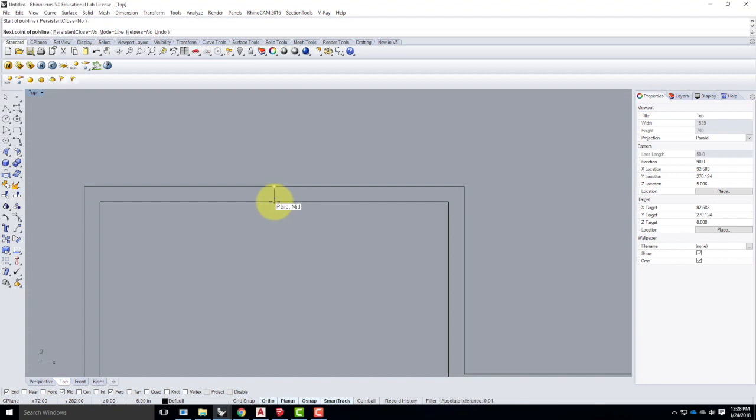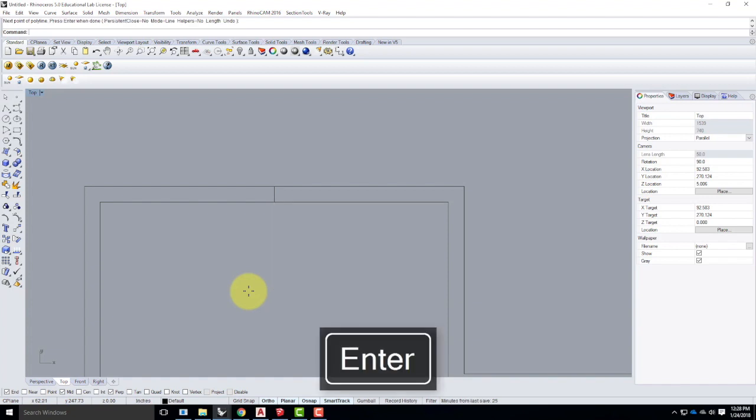But I also have midpoint, and this is the midpoint of that line. So both snaps are being used. Nothing wrong with that. I'll go ahead and click there. And because this is a polyline, I could keep drawing with more shapes. I only need that one line segment, so I'm done. I'll go ahead and press Enter on the keyboard, which gives me that one little line segment.